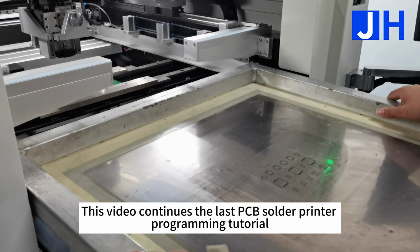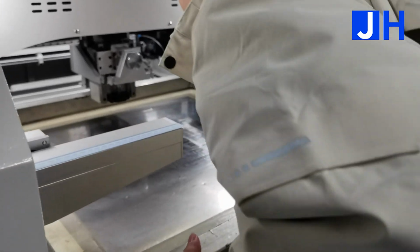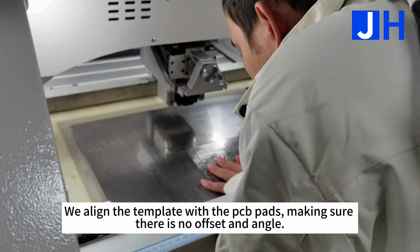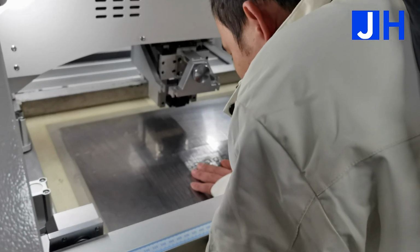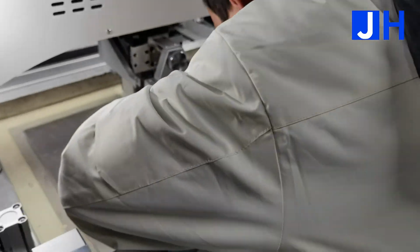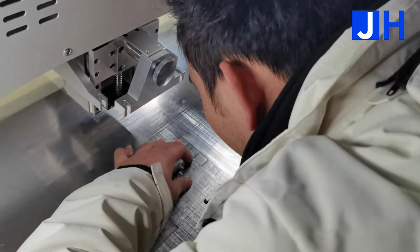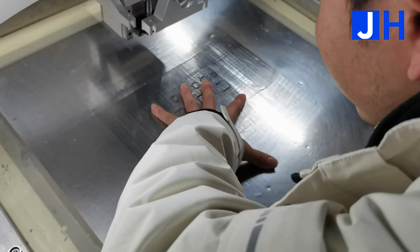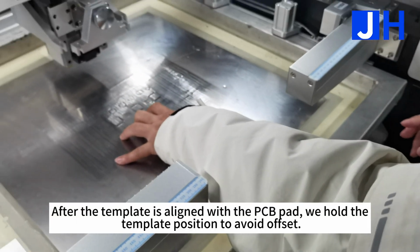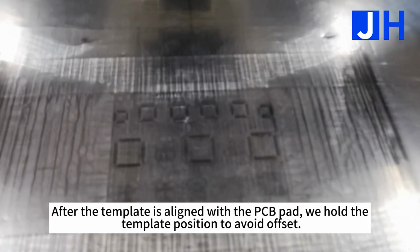This video continues the last PCB solder printer programming tutorial. We align the template with the PCB pads, making sure there is no offset and angle. After the template is aligned with the PCB pad, we hold the template position to avoid offset.